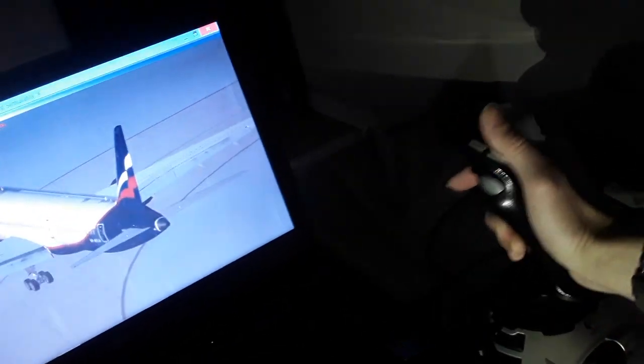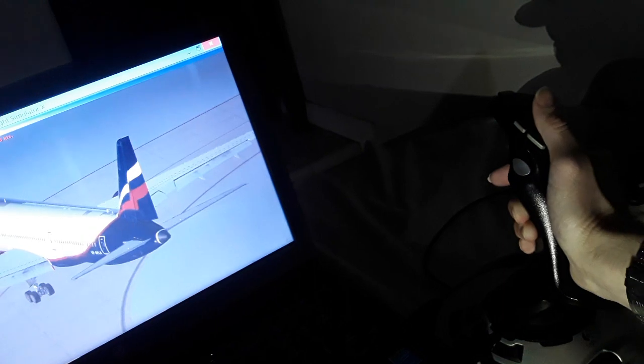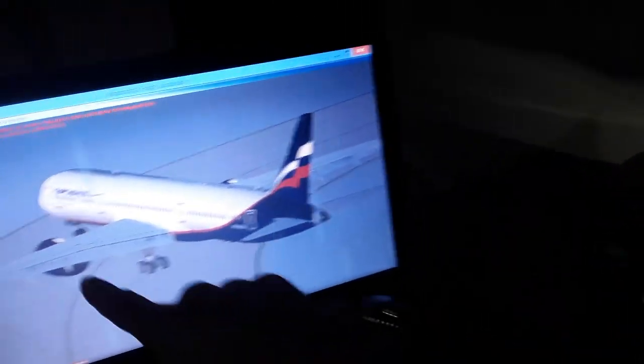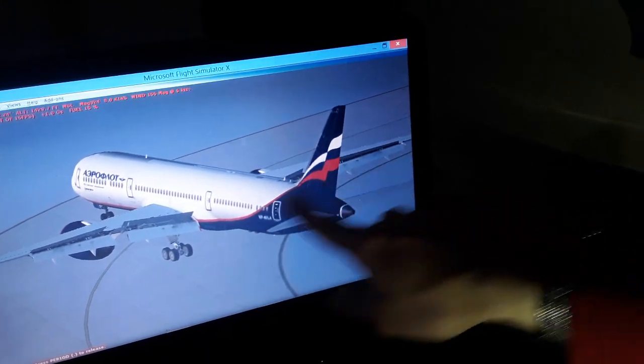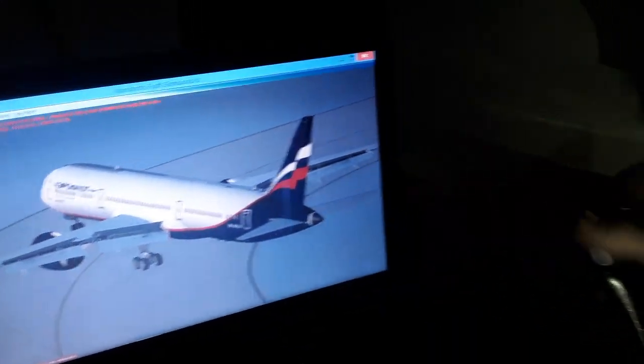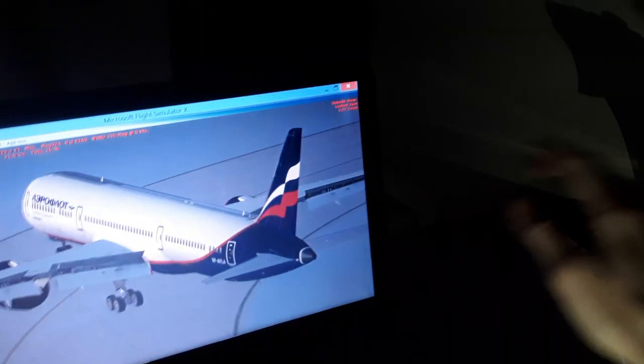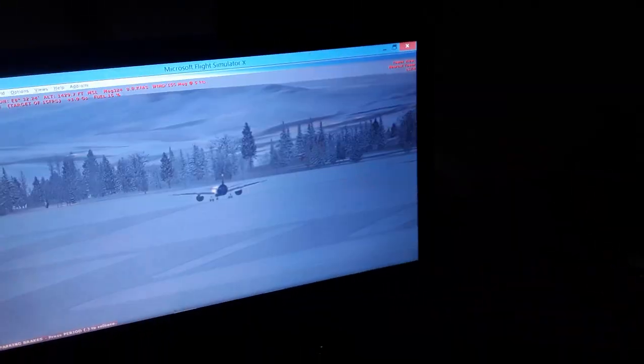So you have all flight controls together, coordinated flight: rudder, elevator, aileron, spoilers. Also you can see the flaps are extended over here, the speed brakes also, the flight spoilers and the flaps with the slots extended. We need the flaps also to increase the lift.